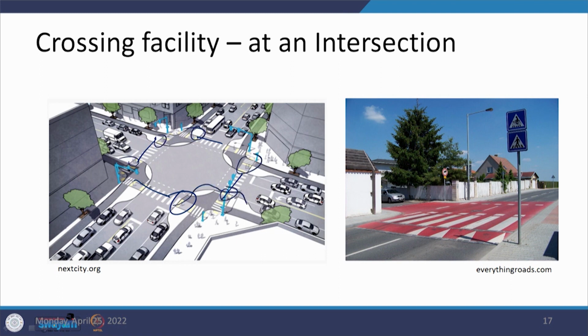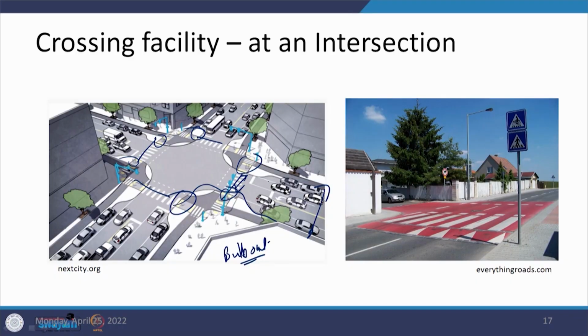There is this approach being provided, which is defined as a bulb out system. What we are doing is that the total width of the road or the carriageway was this much, but it has been reduced to this. So, the interaction time with the vehicular traffic has been reduced, and we are trying to improve upon the safety of the pedestrians. But when you do this bulb type, what you can find is an additional lane is available which can be used for the parking of vehicles here. So, that is one additional advantage you are going to get.